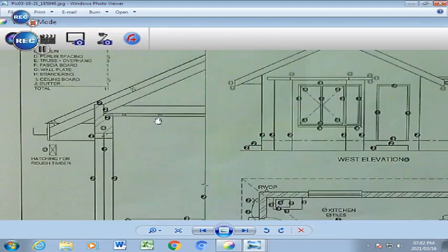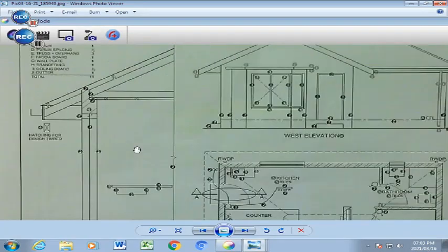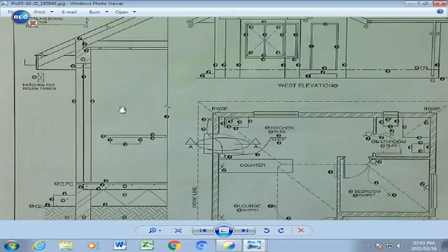And finally, you will find that this must be brought up until the sheeting over there, and that's very important for your beam filling, disallowing birds to nest into this space over here. So that basically concludes this section view.